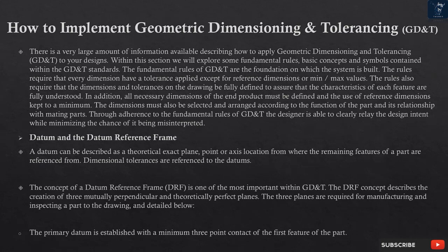Datum and the datum reference frame. A datum can be described as a theoretical exact plane, point or axis location from where the remaining features of a part are referenced from. Dimensional tolerances are referenced to the datums. The concept of a datum reference frame, DRF, is one of the most important within GD&T.